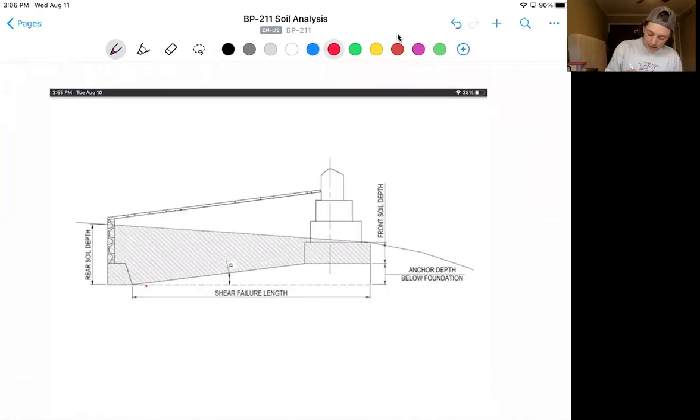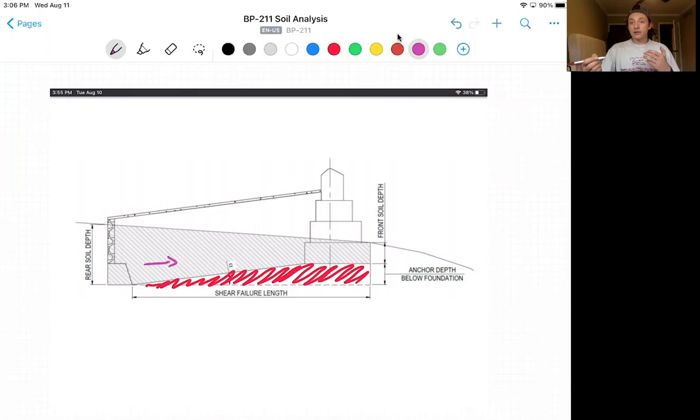And that can be seen with what I'm filling in with red here. So imagine those forces on the anchor pulling in this direction. And as I mentioned in previous videos, to explain the transformation of bottom slope effects, I explain it as a reaction force from this soil slope. Well, that force can cause the potential shearing of this red section of soil off, which is a mode of failure for the bridge.